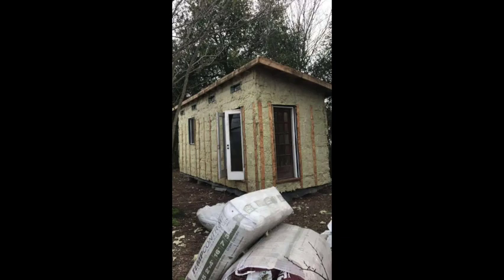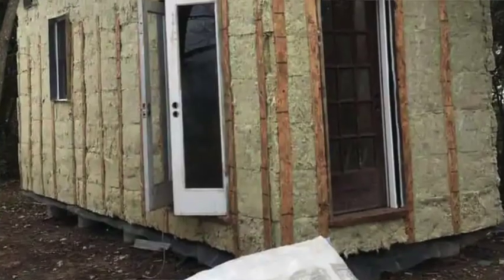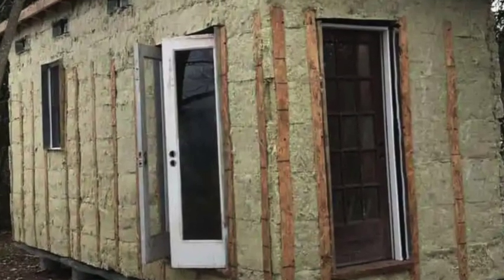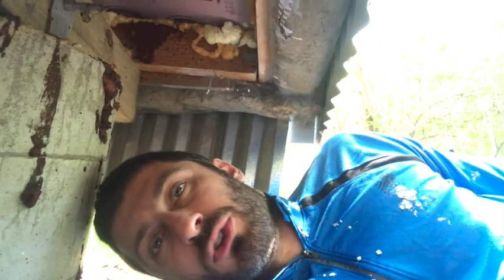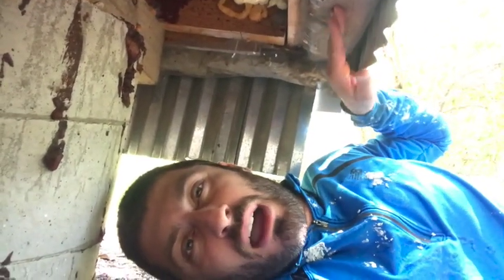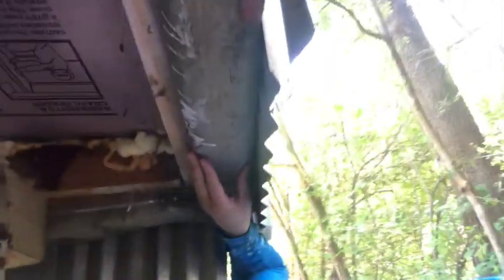The way I was able to pull this off is I used a battening system to stack the mineral wool batts on top of each other, and then I was able to batten them down to the side of the house. That way they hold in place and they don't fall down. And then on the underside of here, I actually have this screening product, if you can see that right there. This is a screen that will stop any bugs from getting in here and will keep the wall free of any pests.